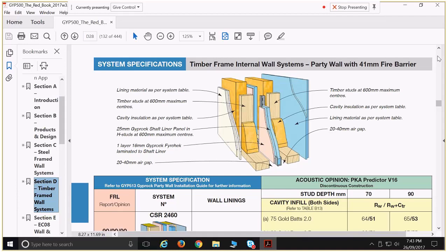Timber type of wood, what's that? No, the timbers are just normal stuff, like the studs. Yes, they are just the normal ones, with a minimum size of 70 by 35.